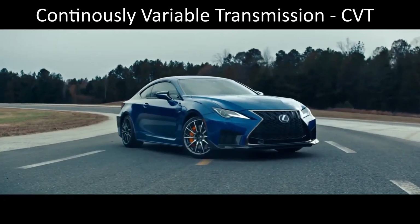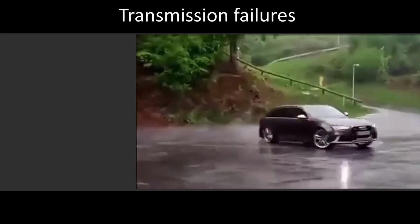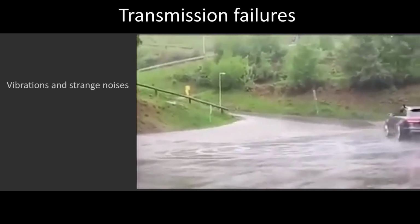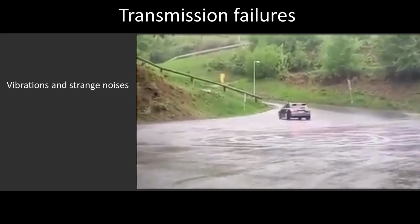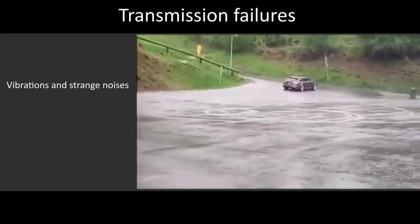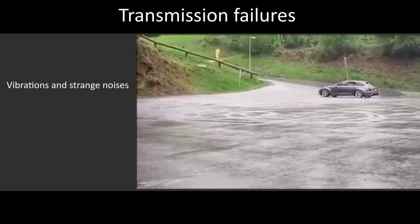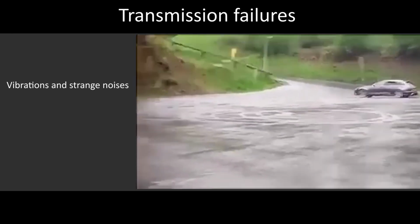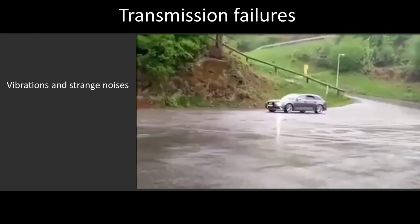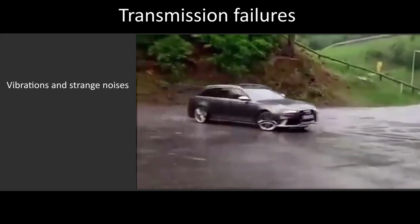Finally, let's talk about the problems related to the transmission system which you may run into. The classic warning signs are vibration and strange noises. If you notice that your car has trouble accelerating or moving at all, but you can hear the engine speed up or rev, it could be the transmission gear slipping. Another warning sign is if the gear stick in your car is difficult to get into gears, causing noises during the changing. In this case, the transmission is either about to fail or has already failed.